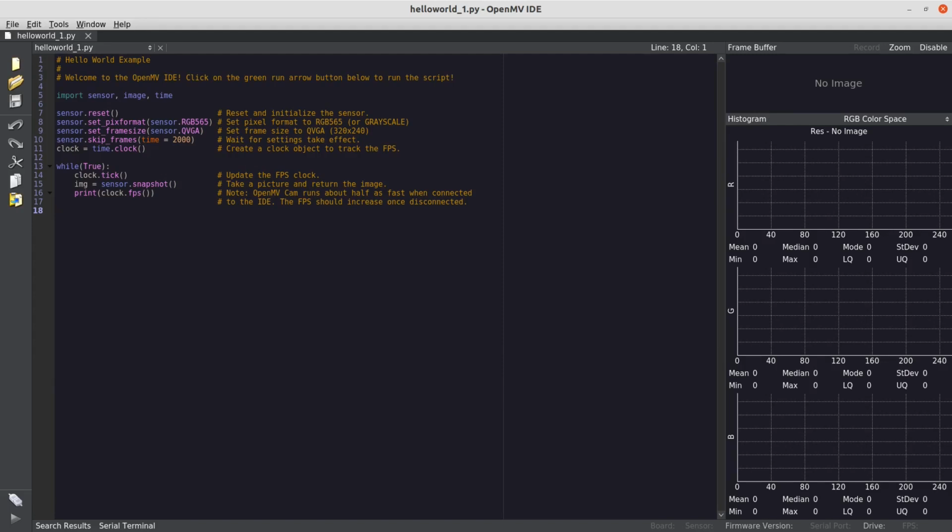Now the next step is to install the MicroPython bootloader onto the Arduino. If you've not used the Arduino before, then potentially it'll automatically go into boot select mode. But if not, or if you've put a program on before, you're going to have to change it into boot select mode. This is normally done by a double tap on the button on the top of the Arduino. If that doesn't work, then you may need to short together the reset and the ground pin when you power it on, and that will do the same.